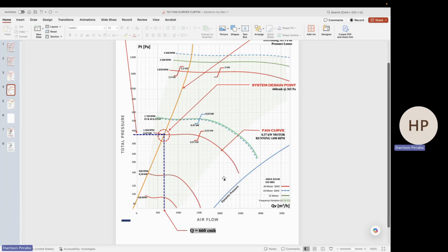This capture distance and the opening of the hood would require a very heavy air, I mean, very high flow rate. So we usually will pick something much smaller, an extraction arm or a slot hood at a very adjacent location, in proximity to the emission. Now, that's good. But regardless of all that, at the end of the day, once we complete the hood flow rate calculation and the static pressure calculation, the selection of the fan plays a far more important role.